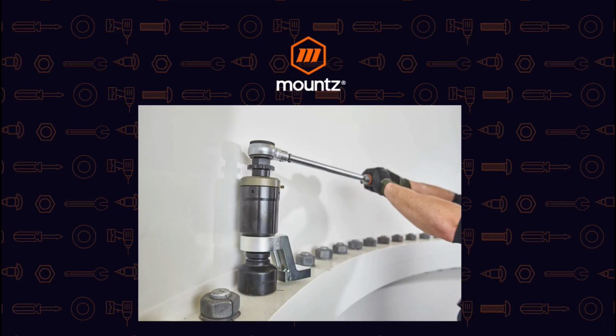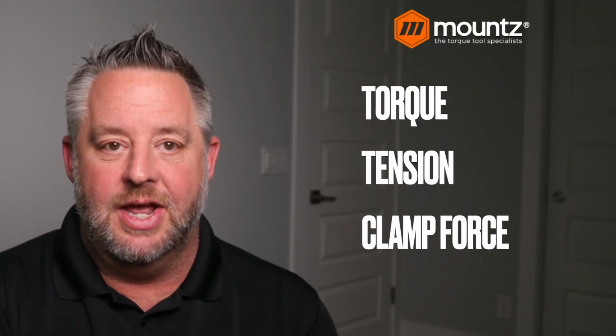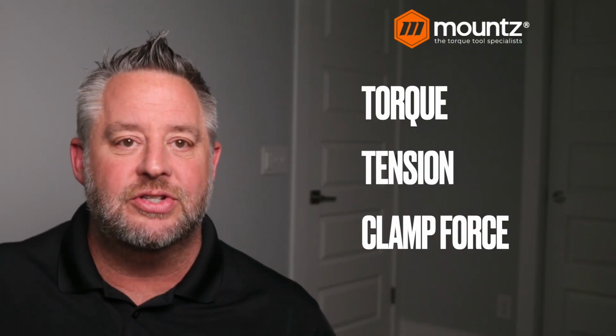So different ways to achieve the same thing, which is we're trying to use torque to create tension in the fastener, which is trying to get us to the correct clamp force that we need to be able to hold our parts together, which is what we're truly trying to achieve in the end. So that is going to conclude our basic fundamentals of torque.